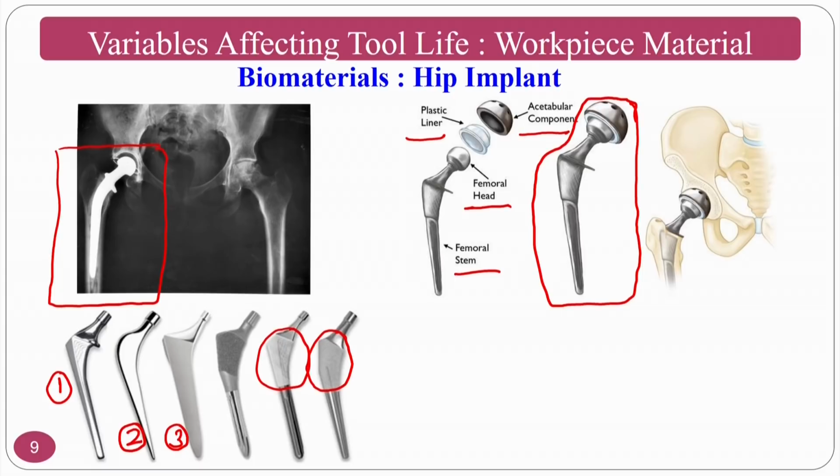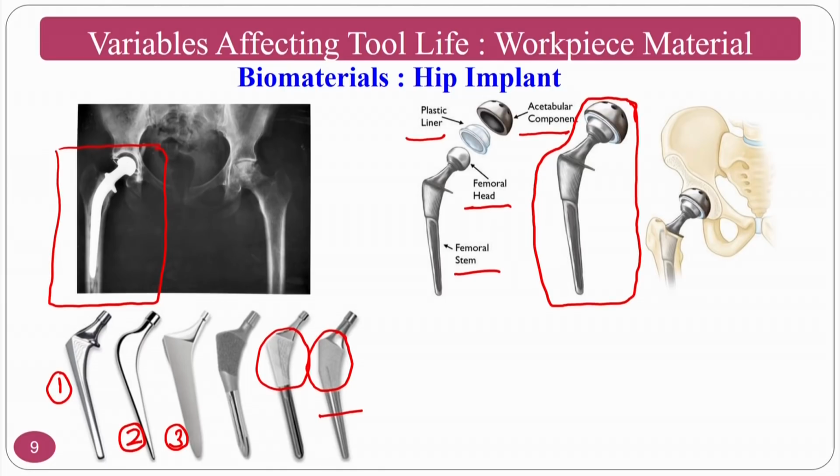Another one is surface metallurgy. As I said, surface integrity is nothing but the surface roughness and surface metallurgy. Okay, if I don't heat or the hot chips are not coming, that means the surface of my product will have better surface roughness and surface metallurgy. Both things will be very good.